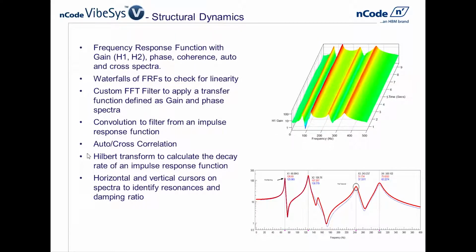Another interesting application in VibeSys is to do with structural dynamics. So we want to characterize a structure knowing its excitation and its response. There may be many excitations, many responses, and for each couple of excitation and response we get this famous frequency response function, which is a spectrum indicating specific frequencies that are amplified due to modes, for instance. So this can be displayed in the form of a gain spectrum.